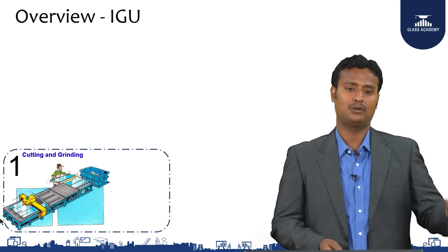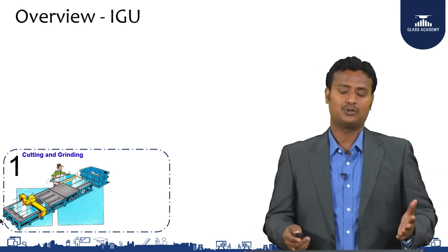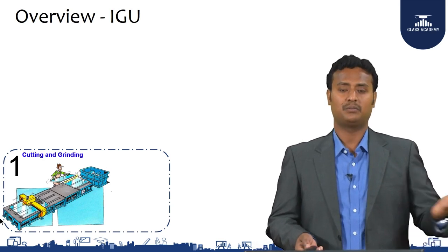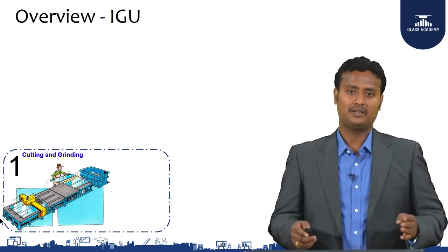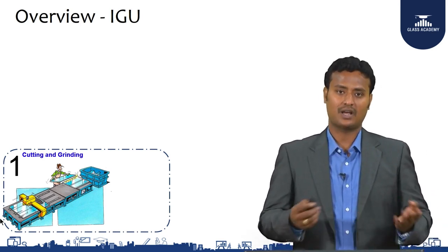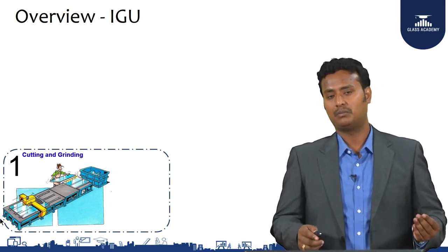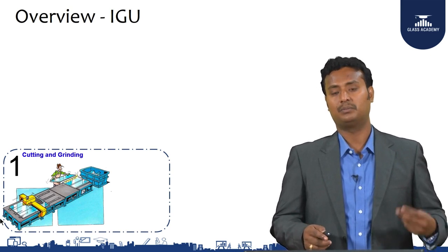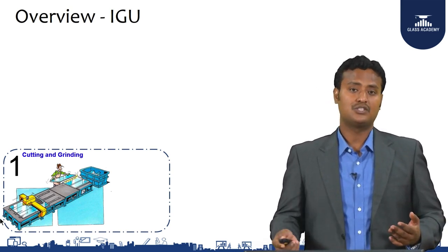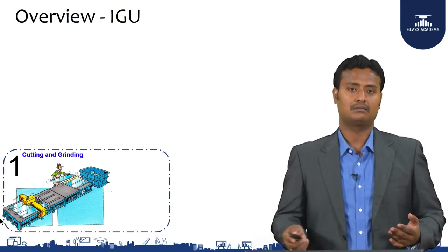You have to keep it on the loading table. Order size you want to do, so you have to optimize, cut it and snap it, and then store it and grind it. The grinding is most important, because if any shell forms or the grinding is not proper, the glass tends to break at the tempering section.